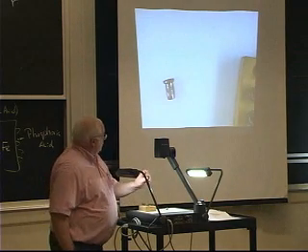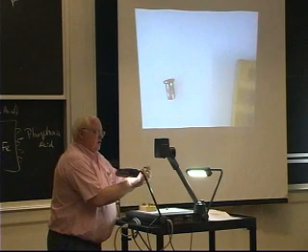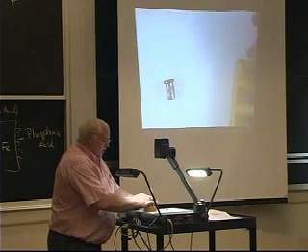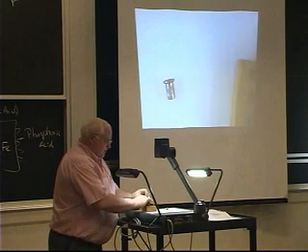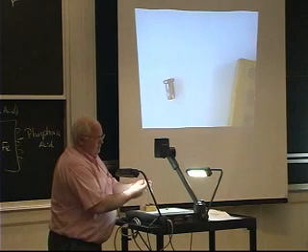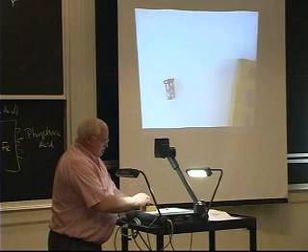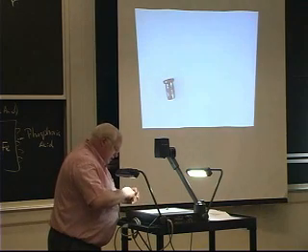Then they start an extrusion process and start to make a little hole. So this one's a little taller than that one because they back extruded part way. And then they back extrude some more and make it even taller. And then they put a head on the end. And this one's still got a little hole in the bottom.